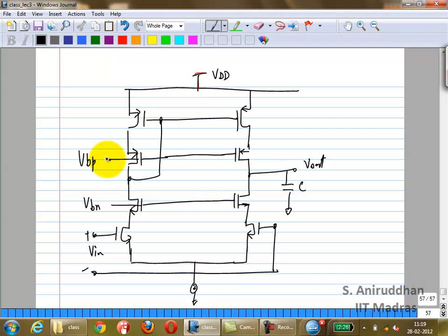Okay. So suppose you need to write the poles of this op amp. So now we know we are going to get poles, right? So where all will you get poles? First of all, at the current source node, it's going to be the same as before, so to a large extent, you can ignore that. You'll get a pole here. We already had a pole there, so at the current mirror node, we're going to have a pole here again.